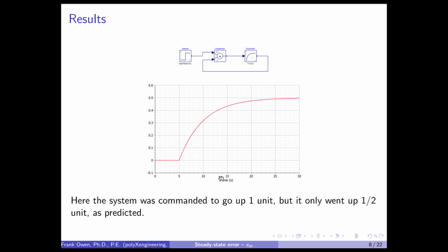Now, what I did was I actually ran this example. I put in a time constant of 10. That's just kind of random too, just to have an example. But I have a unit step input that I put in here, and I've closed the loop around the inner first order system. Now I've not put in Kp and Ka because they're both 1, so I've just included them both in our system here.